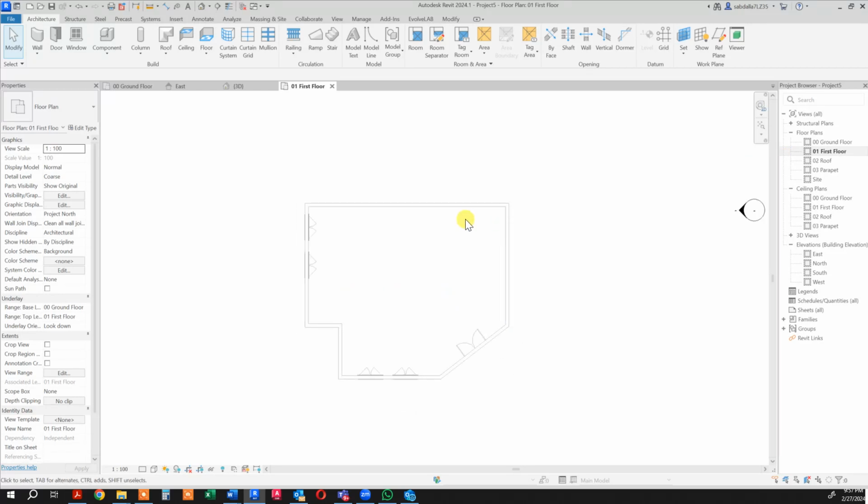Now you could see the ground floor grayed out a little bit, but if you don't see it, you need to go for something called underlay. Sometimes your underlay is set to none. You don't see it, so you only see it here for tracing, to build your upper floor. So let's create different settings here.